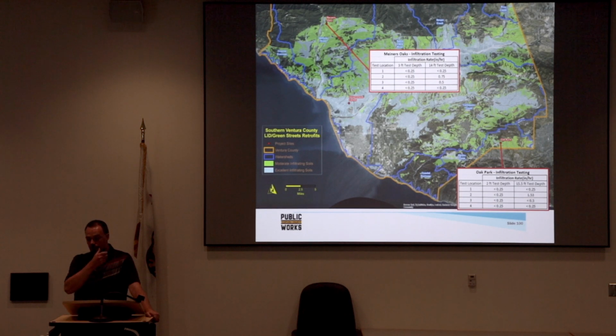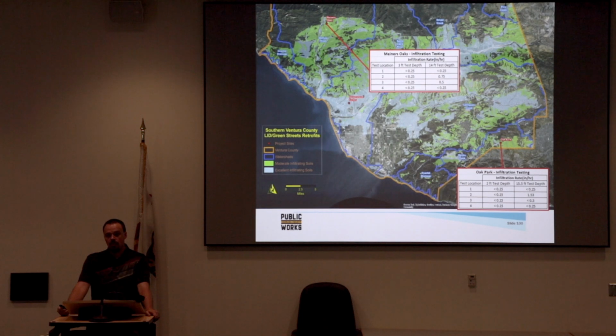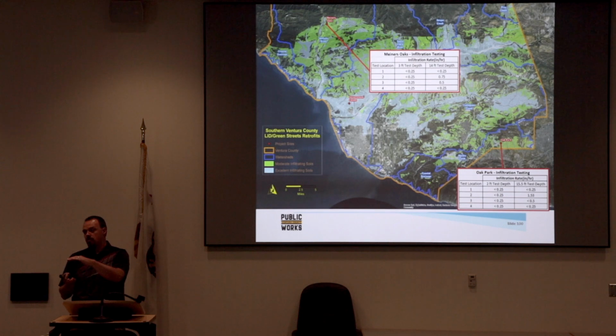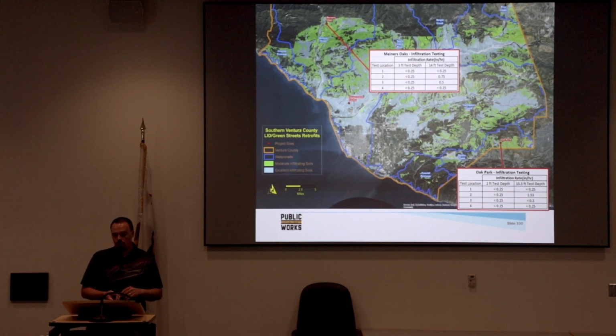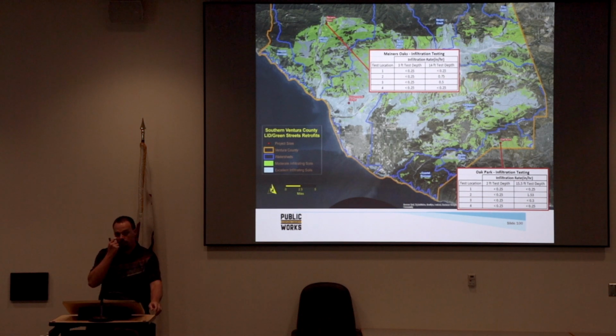In this project for Oak Park, it's another grant project we did. Initially, we wanted to do infiltration again, but when we went back and did infiltration testing, the same thing occurred. It's supposed to be soil number 4, which would be good for infiltration, but same thing, we found just clay everywhere, all the way down to, I think it's 15.5 feet on this slide. Even though we're just testing, it's like a 1-foot area at 15 feet, so it could be 14 to 15 feet, that's the area we measured, or at the 2-foot depth, it'd be 2 to 3 feet or something. Like there's a 1-foot area where we're measuring that depth.